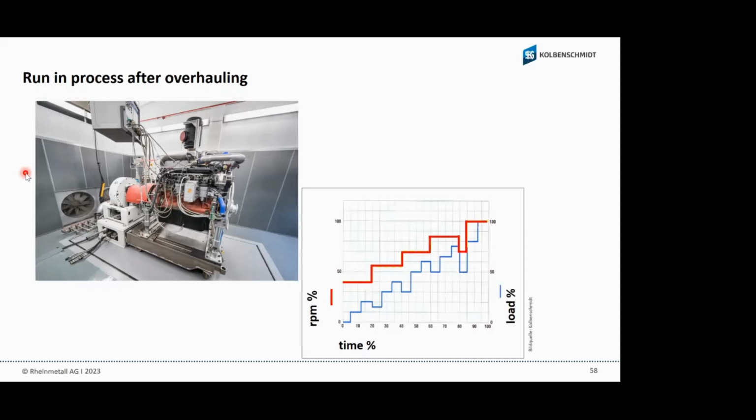The next effect is when you run the engine at idle speed. You do not get this running-in effect so quickly. And the other effect is that they do not seal perfectly between the combustion side and the bottom side, and then oil comes into the combustion chamber and burns and builds up carbon. And when we build up carbon, we polish the cylinder bore, and also in a bigger situation with more carbon on the piston ring or the piston ring groove, the piston ring cannot move in the groove. And then they stick, and then they also have wear.